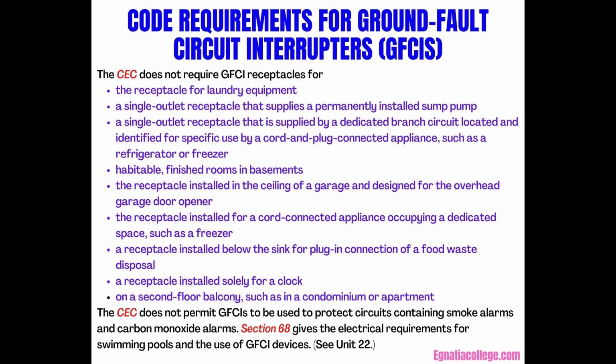A receptacle installed below the sink for plug-in connection of a food waste disposal. A receptacle installed solely for a clock. On a second-floor balcony, such as in a condominium or apartment. The CEC does not permit GFCIs to be used to protect circuits containing smoke alarms and carbon monoxide alarms. Section 68 gives the electrical requirements for swimming pools and the use of GFCI devices.